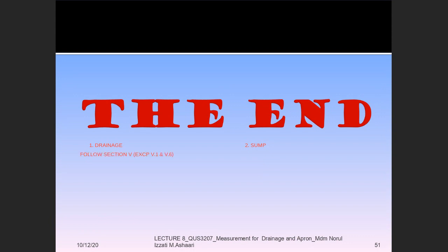That means we have to start from the trench excavation, and then you have disposal of water, and then you may have the beds or benching or covering, but normally for the perimeter drain, we have beds only. After that, you have to check what is the surface water channel. The word channel refers to half round channel, or this also refers to the pipework. They need to be measured in meter.